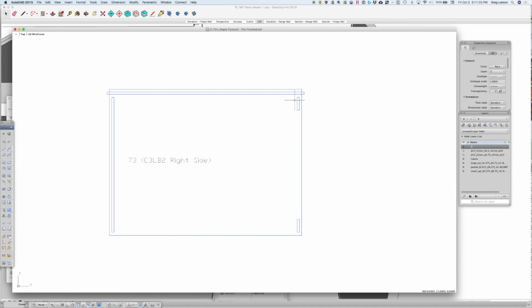So in the case of these where the tenons go into, if you recall, they're cut to the full width, but they're going to end up with a little radius in here, so we undercut the tenons. And for this groove, it goes all the way to the end, but if we stopped our bit right at the very end here, we would have a little chunk of radius still left there.